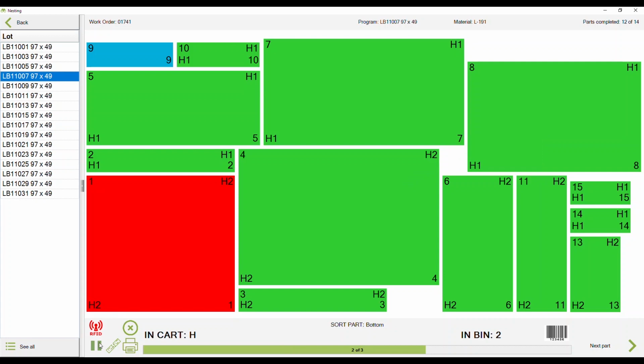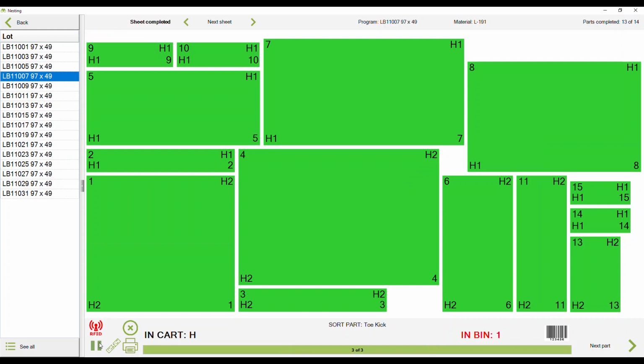So it optimizes not just getting out the labels, not just changing status, but also being able to group the parts for the next operation, let's say the edge banding. In a small shop process like this, what's really interesting is that they're able to start cutting the parts at the nesting machine and organize them for the edge bender or the doweling machine. The guy can already start working on these parts without having to wait for everything to be cut, because they're all grouped and organized, and he knows which one he can grab and start sorting into the rack.